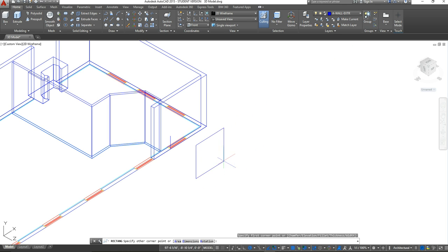Once you click one time, because we know our dimensions, I'm going to go down here and select dimensions. It's going to ask me for some length, what that length is across. Again, we want that to be 3 feet. I'm going to press enter, and now it's going to ask me for that width, and I want that to be 4 feet 6 inches. Again, that's just from that illustration we looked at. Okay, and I'm just going to place that rectangle down.